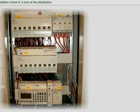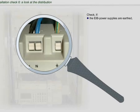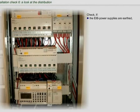A visual check must be done to ensure that all EIB KNX power supplies are connected to the protective earth conductor. A minimum clearance space between insulated wire cords of mains cables and those of EIB cables must be observed. For this reason, the unused sections of a data rail should be covered by a data rail cover.